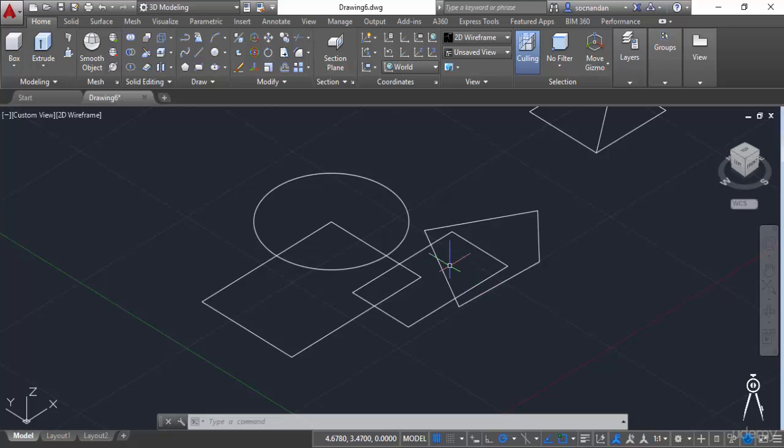But for the press pull command, all these restrictions do not exist, and you can select the islands between objects for making a 3D object. Let me tell you that with an example. So here we have this press pull command. Select this command, and now instead of selecting the geometry, move your cursor inside the area. Now I have moved my cursor inside this area. I'm not clicking on any geometry, and let's click.